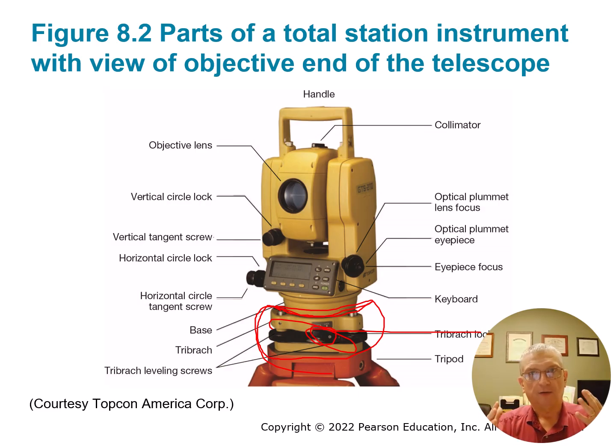And then you've got fixed targets that don't move, that are not subject to the wind or to humans not being totally in plumb. The weakness to this is if your optical plummets are out just a little bit, you can pick up some instrumentational error that we will talk about later in this lecture. And obviously below here, the leveling head is on the top of the tripod, which is sitting down below.